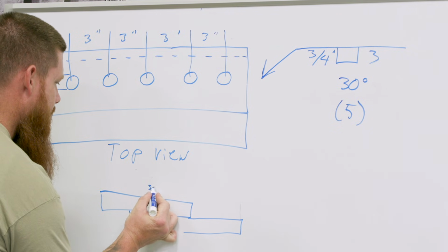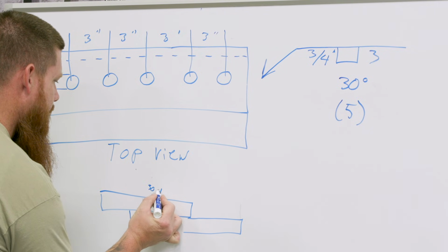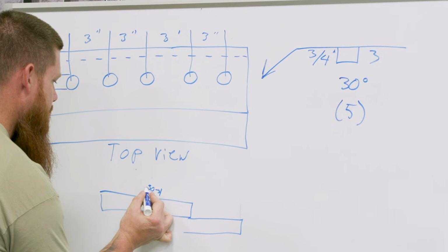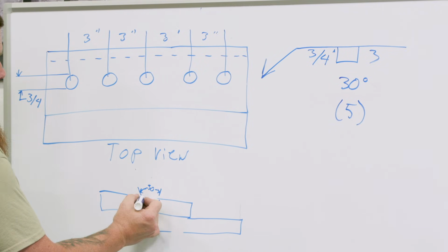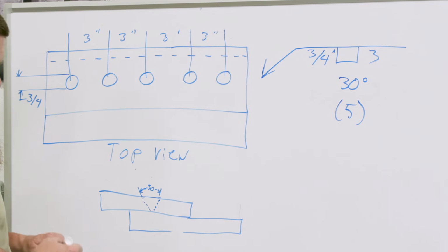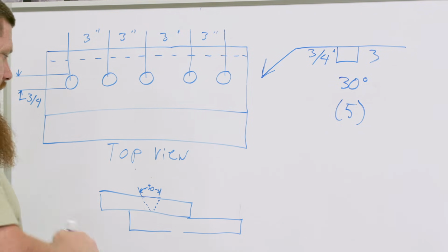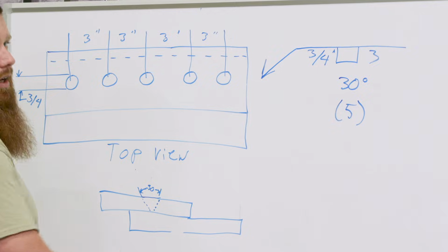And these will be usually machined, okay? You're not going to do this with your torch. So now we have our 30-degree opening in here. We'll be able to set that in there and then fill that in accordingly. And you're just going to fill this whole thing up.